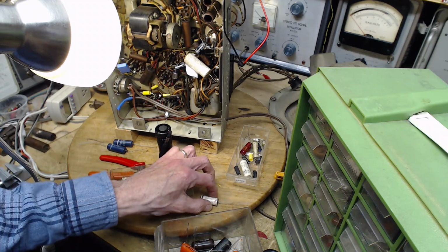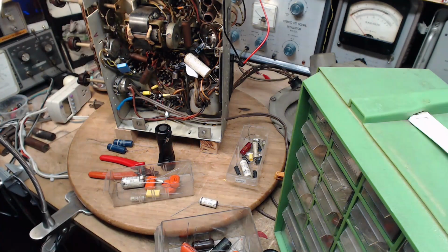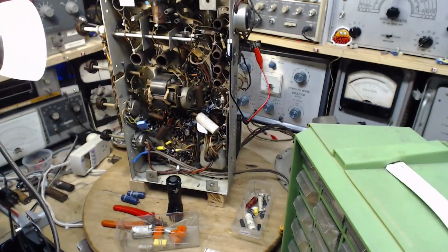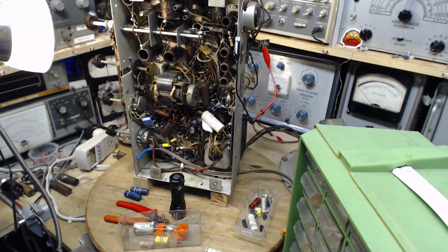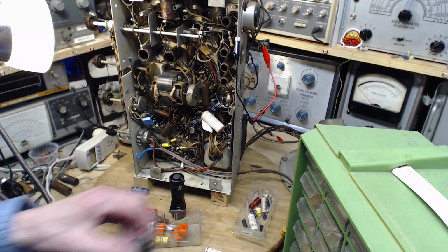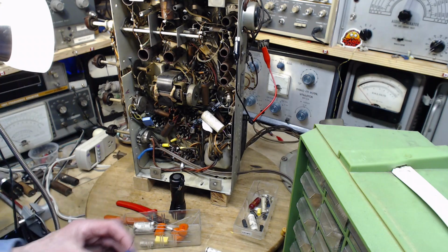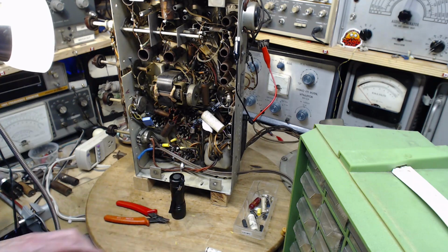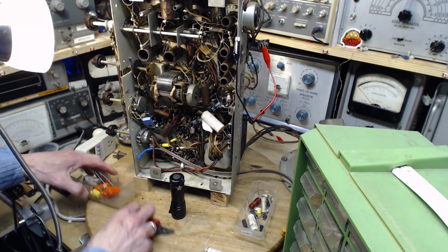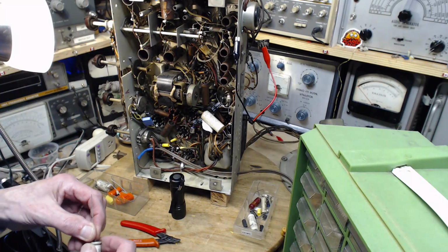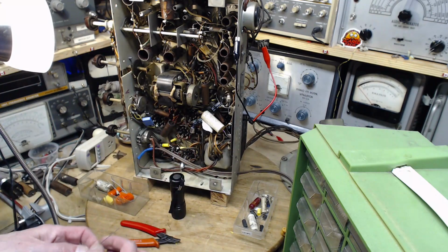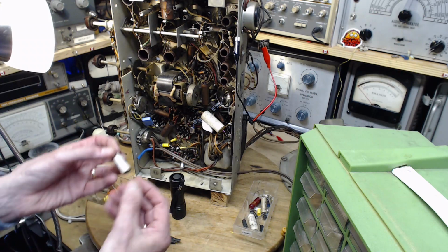I guess what we could do, it's too bad I didn't read the voltage before taking that capacitor out of there. Screens are usually a little bit less in voltage than the plate. Not always, but in most cases. You need the screen to be a little lower voltage than the plate. I also have these guys. They're also 200 volt. They don't look nearly as good. Okay, I think that's what I got to do. Too bad I took that capacitor out. You know, I should have hesitated, found a new one before I took the old one out. That might have been a better way to go.